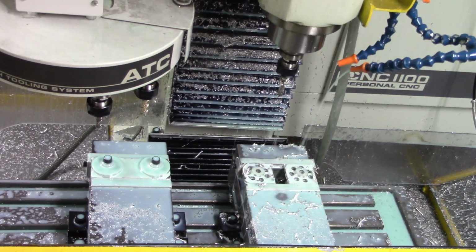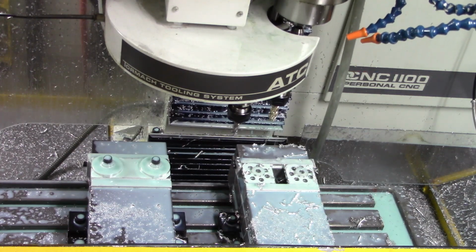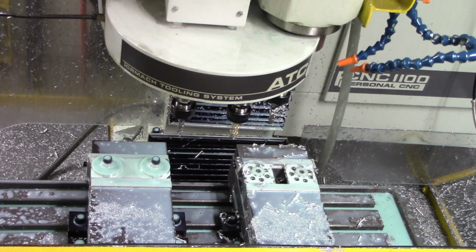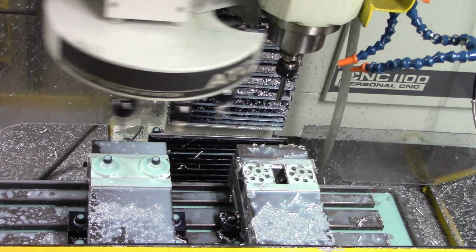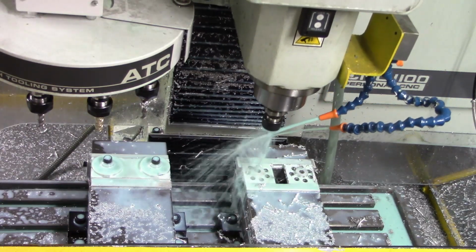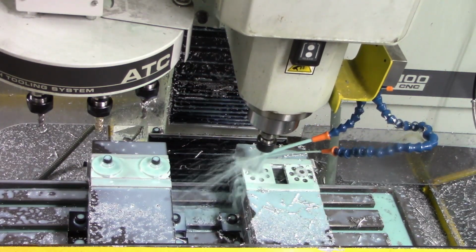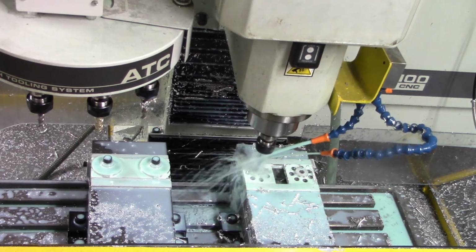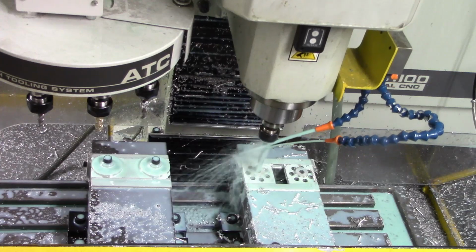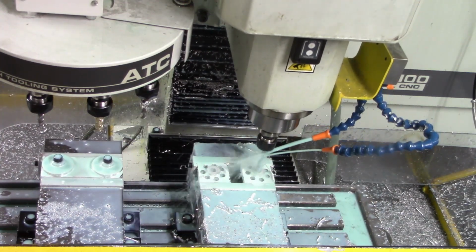Got a tiny little bit of buildup on the cutter, not much. I try to optimize my peck cycles, feeds and speeds to make short, thick, broken chips as opposed to long, stringy, continuous chips. Reaming at 250 RPM, 5 inches per minute, with a 3/8 straight flute reamer.